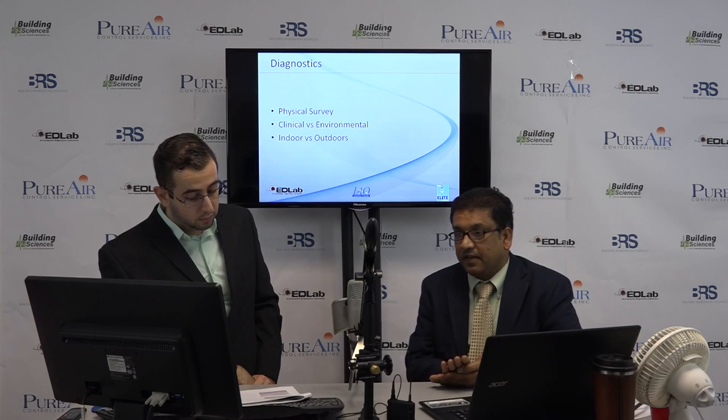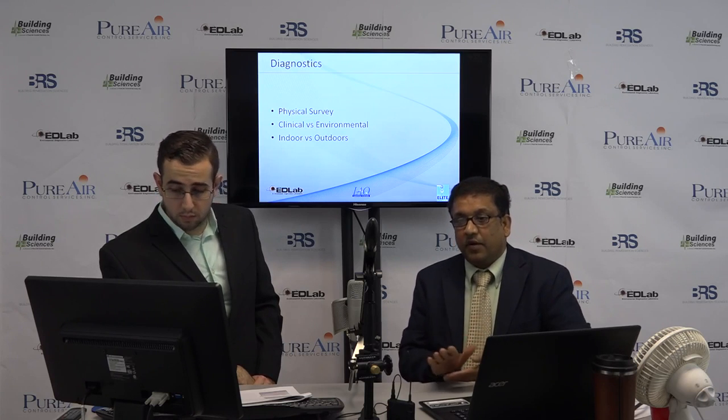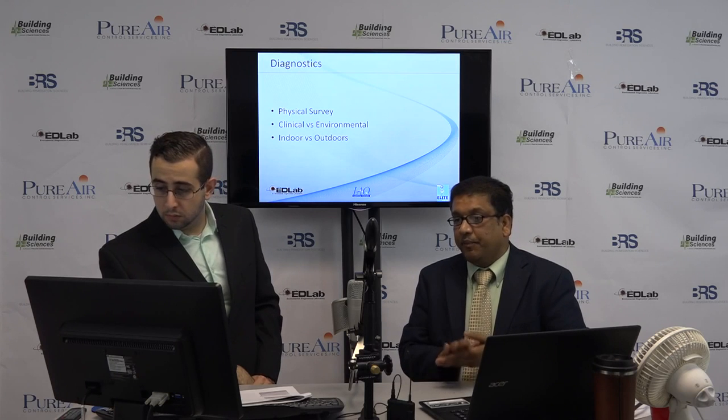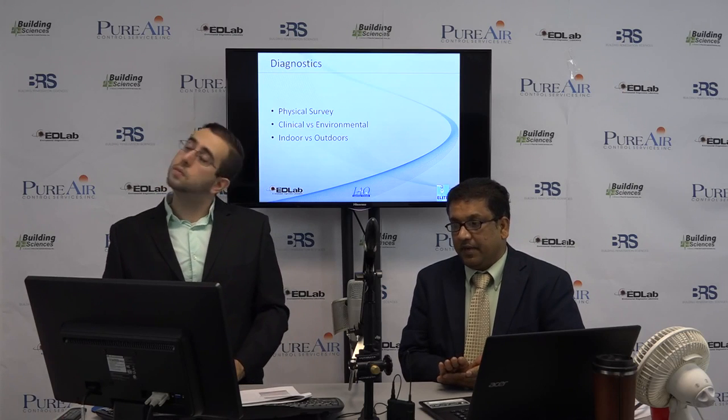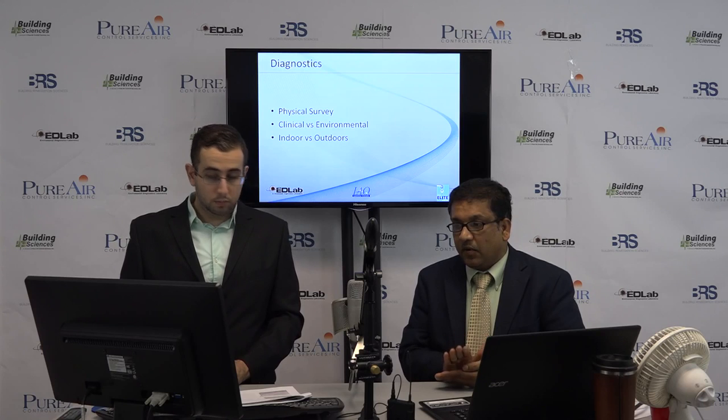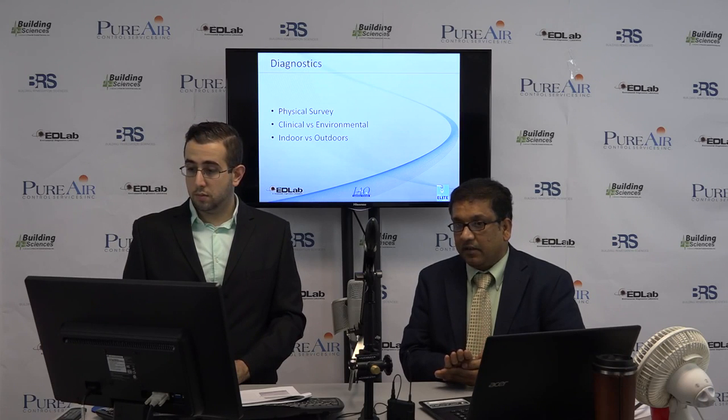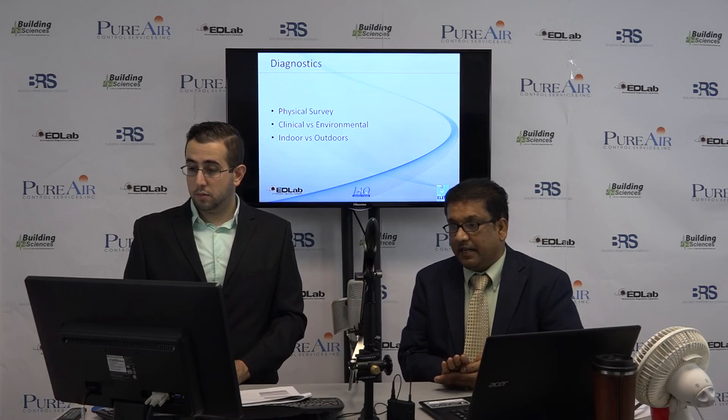When I say physical survey, meaning that you are going around that particular building and you are making sure how the water system is being laid out in that building, and that is very important. I will discuss that a little later. Then you should also keep in your head that you are investigating or exploring or taking the Legionella test due to the clinical concern, or basically it is something environmental in nature.